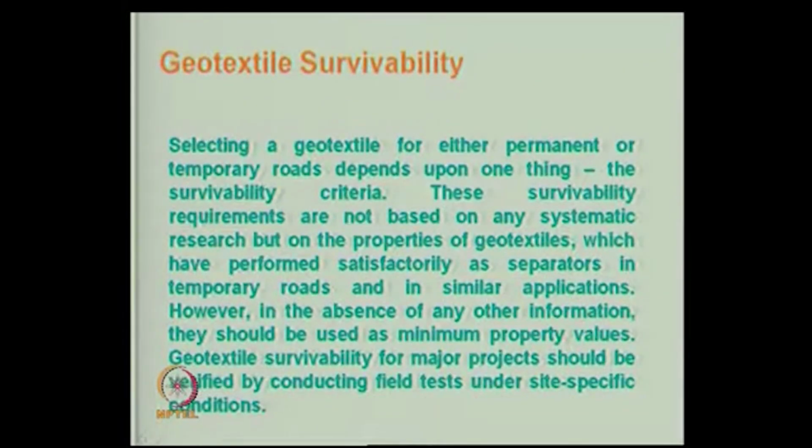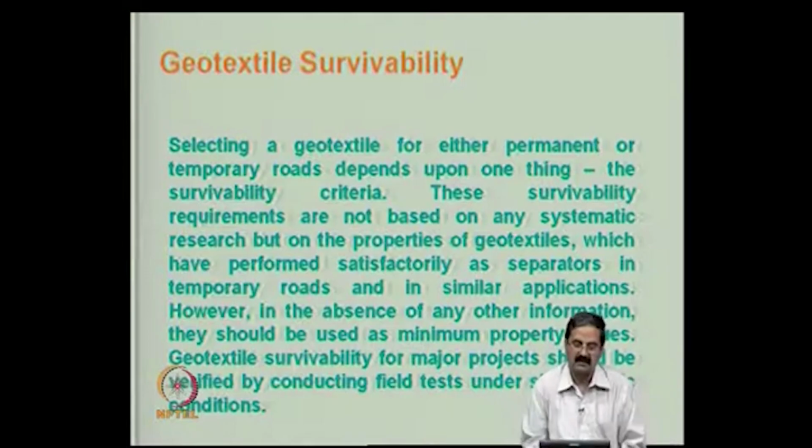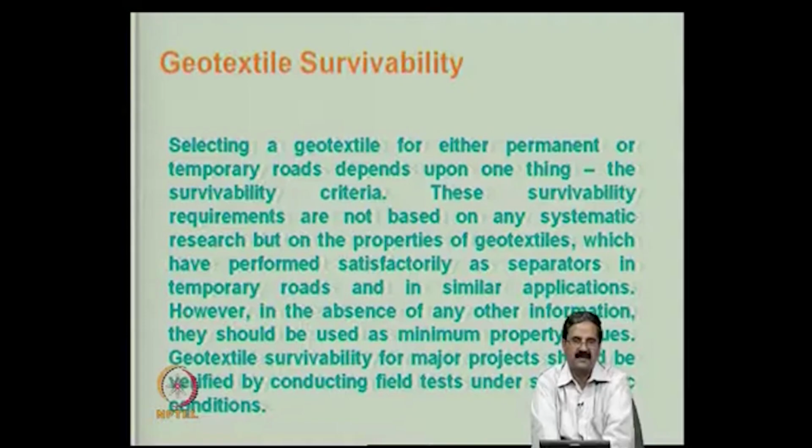Now, as I just mentioned, survivability of the geotextile we just discussed, and selecting a geotextile for either permanent or temporary roads depends on the survivability criteria. The survivability criteria are not based on any systematic research, we should accept that, but are just the properties of the geotextiles which have performed satisfactorily as separators in temporary roads and similar applications.